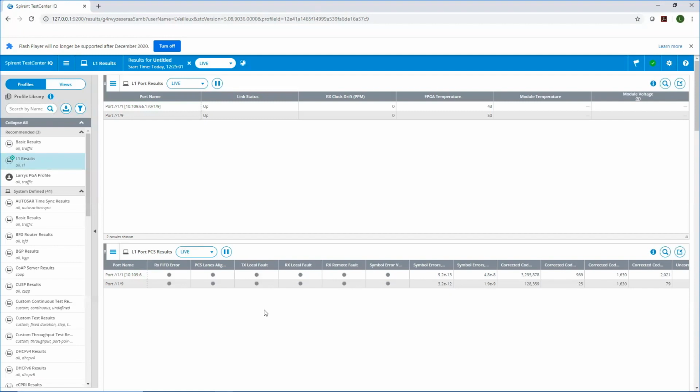In addition, the Clear PCS History button will clear the LED status. The LEDs provide a single event status, whereas green indicates good and active, yellow indicates there is intermittent behavior. And after selecting Clear PCS History, it will display the most current value.